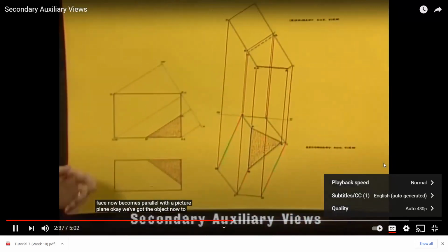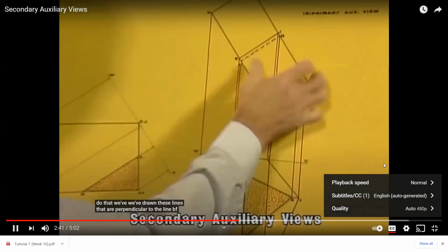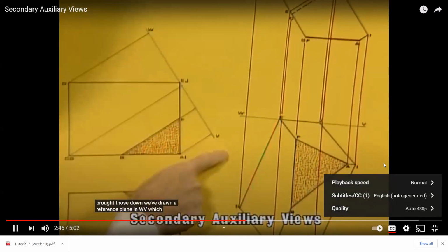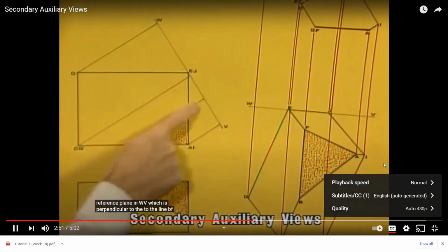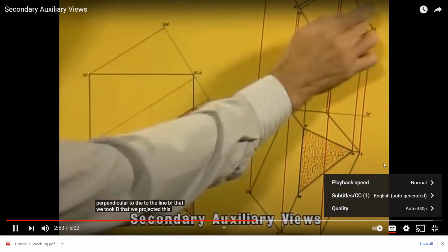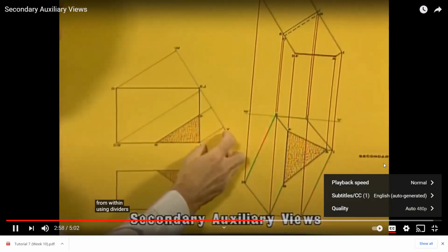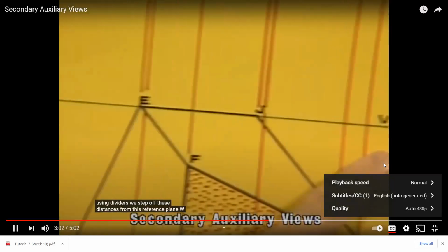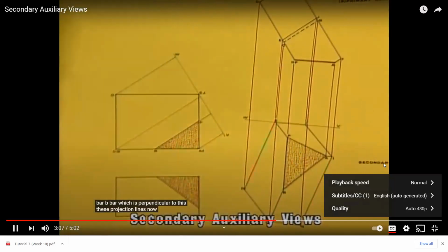Now, to do that, we've drawn these lines that are perpendicular to the line BF. We've brought those down. We've drawn a reference plane W bar V bar, which is perpendicular to the line BF that we projected this view from. Then, using dividers, we step off these distances from this reference plane, which is perpendicular to these projection lines.